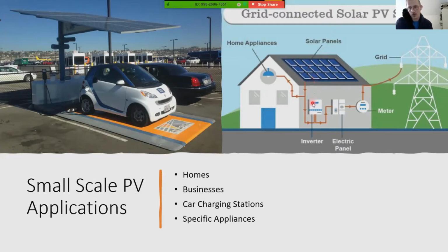One thing to consider is you can either have one inverter that handles all of your panels, or each panel can have an individual inverter. I would recommend having an inverter for each panel, because if you only have one inverter, then anytime there's partial shade on one of your panels, the inverter basically has to drop to the lowest denominator and provide power based on that. I didn't quite fully understand the concept, but basically if you have an inverter on each panel, it maximizes the amount of power you can get, as opposed to just having one inverter for your entire solar system.